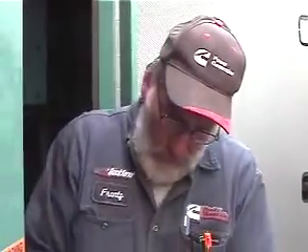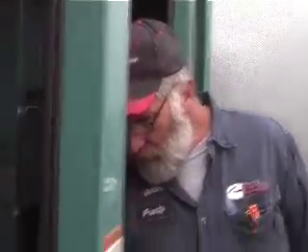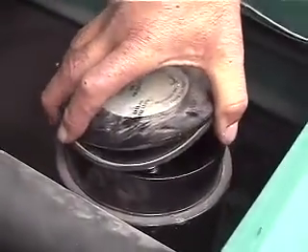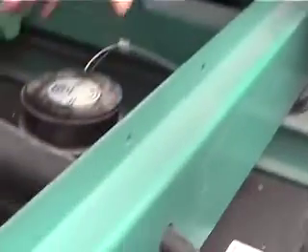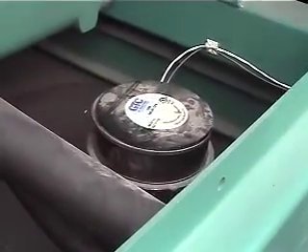The gauge is not extremely accurate because it's up out of the tank just a little bit because of the weld-on fitting on this stuff. So usually you're off a little bit. You guys are probably used to that. This cap you're seeing right here, this is what I call an anti-shrapnel vent. It's an emergency blow-off vent, so that in the case of an explosion inside it, rather than the tank bulging in an explosion type thing, this will blow off, and it's supposed to let out enough gas so it doesn't do that to it.